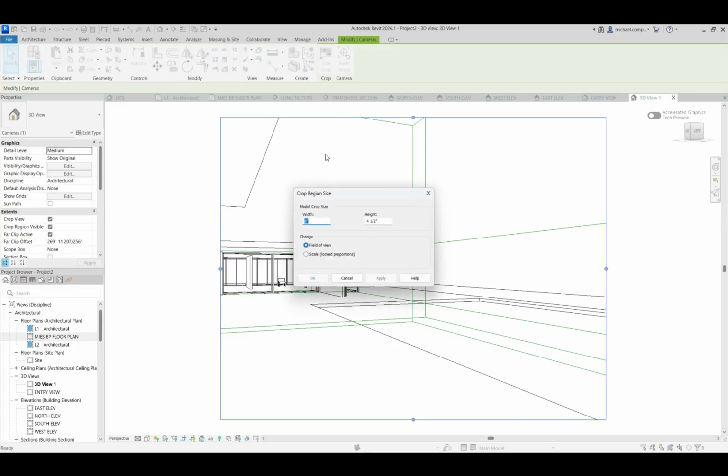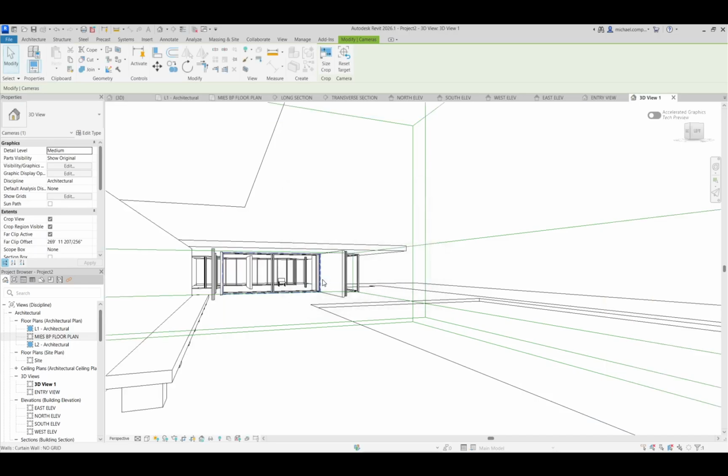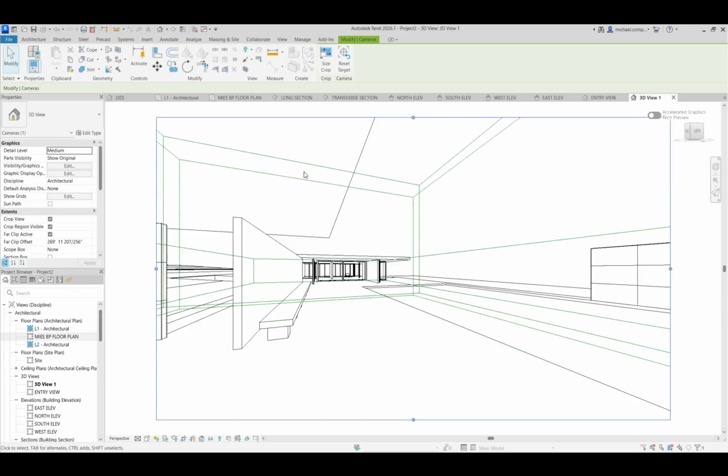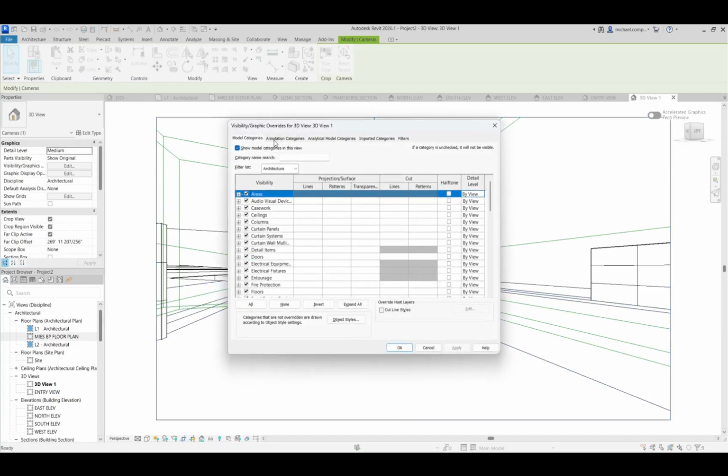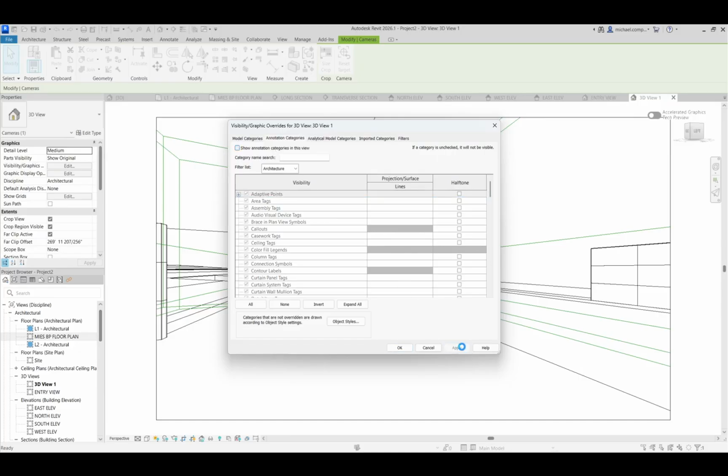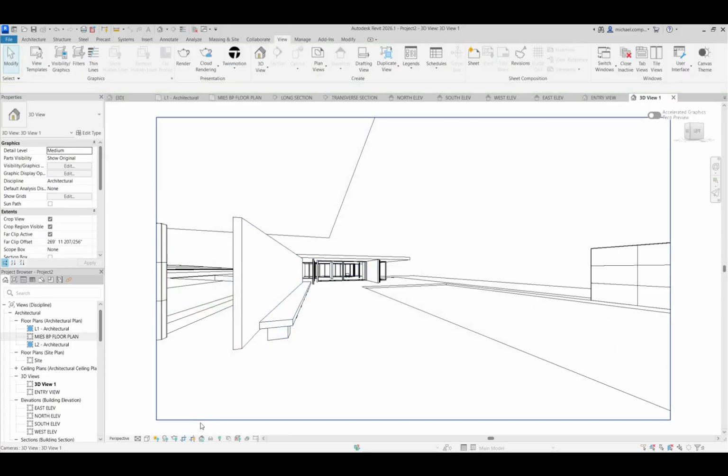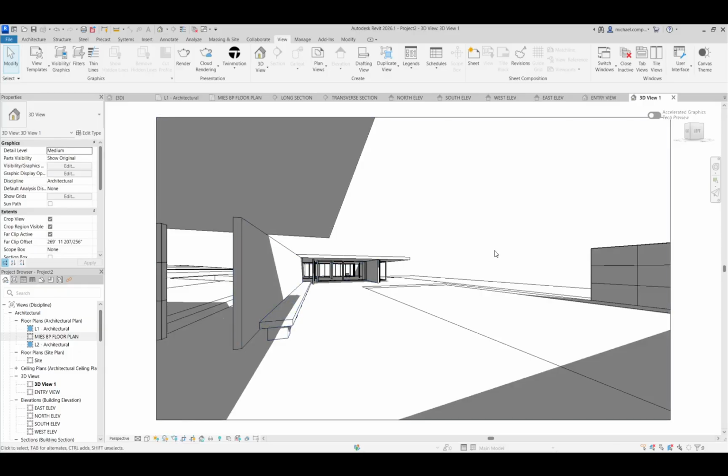And then similar process, 16:9. Apply it, OK. ZE for zoom extents. I'm under the roof, looking past the stools at the storefront, and just see a little bit of this edge in the reflecting pool, right? VV, I'm going to turn off all the annotation stuff, which I don't need, and then I'm going to turn on shadows. I'm in shadow, so that's great. I now have my views.